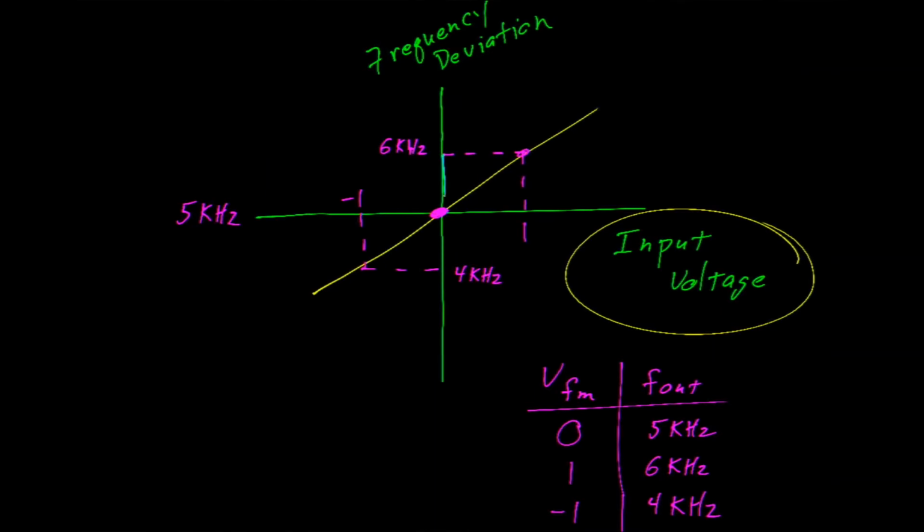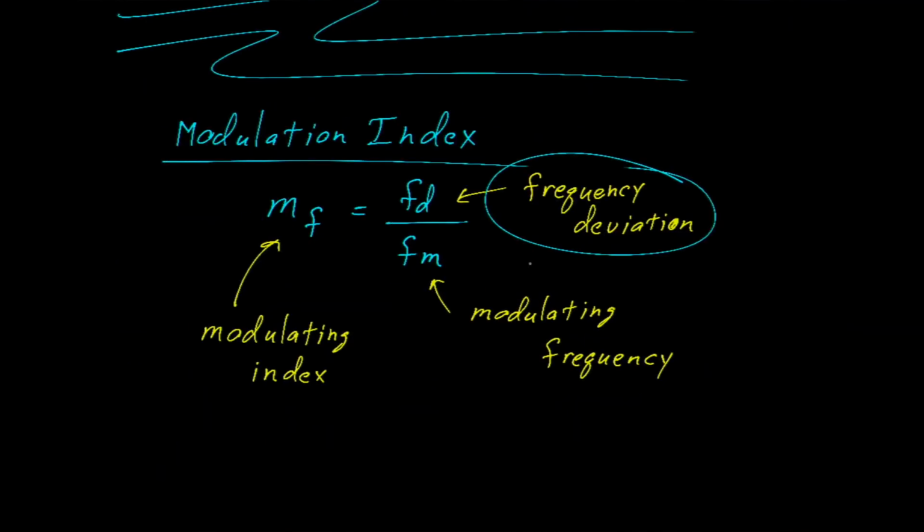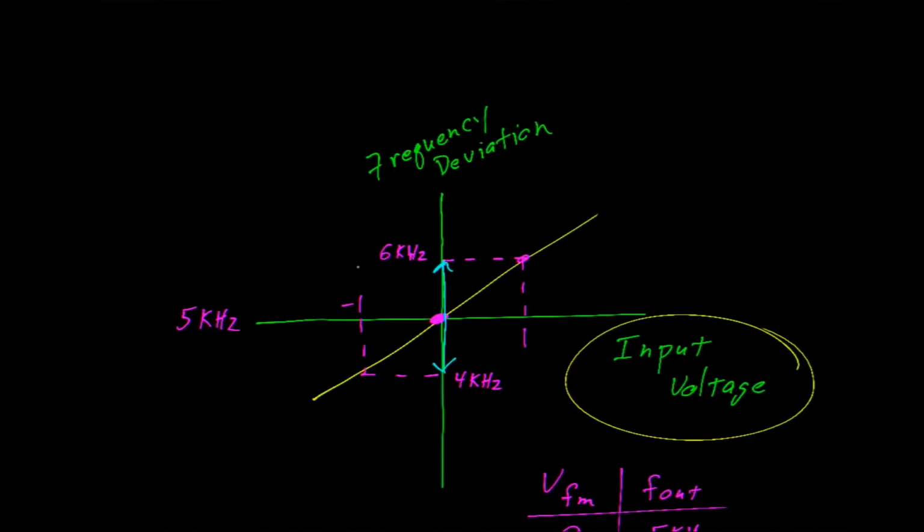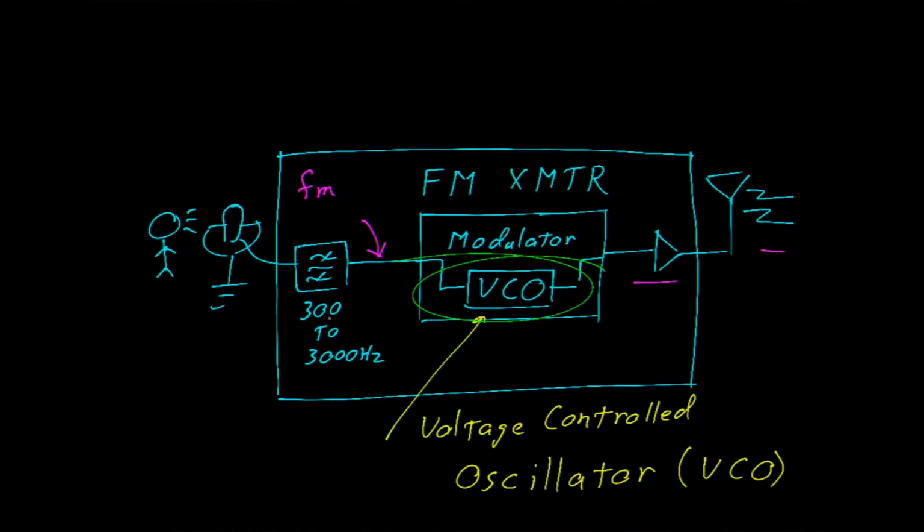As the transmitter changes output frequency, what is this upper number and what is this lower number? The modulating frequency asks how fast the tone is changing. For that, we have to go way back up to our original diagram. If you are at the bottom of the voice frequency, the modulating frequency is changing at a rate of 300 Hertz. At the top of the voice frequencies, the modulating frequency is changing at a rate of 3000 Hertz.